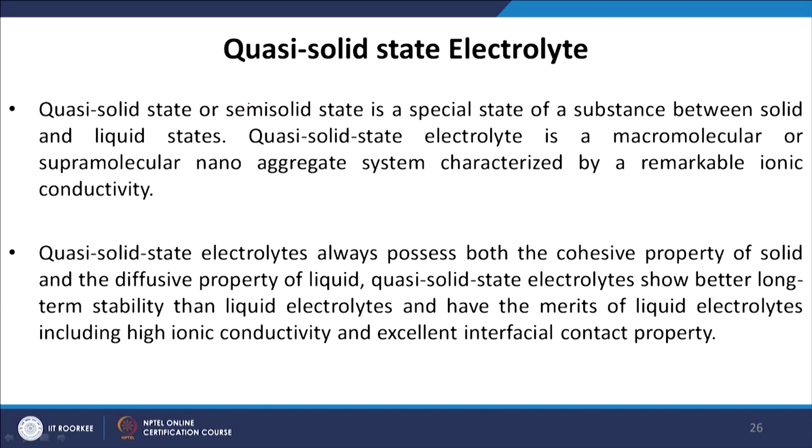Quasi solid state electrolytes, or semi solid state, are a special state of a substance between solid and liquid states. Quasi solid state electrolyte is a macromolecular or supramolecular nano aggregate system characterized by a remarkable ionic conductivity. So, quasi solid state electrolytes usually have a very high ionic conductivity value. They always possess both the cohesive property of a solid and the diffusive property of the liquid.